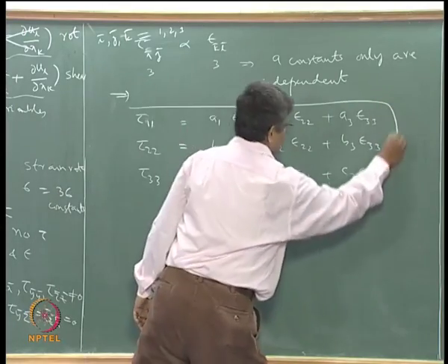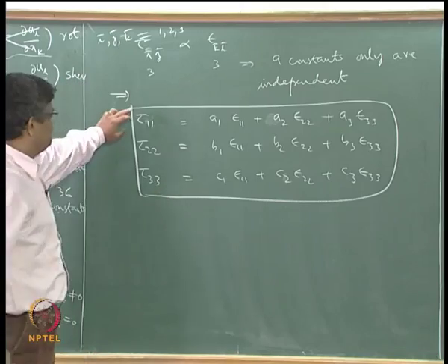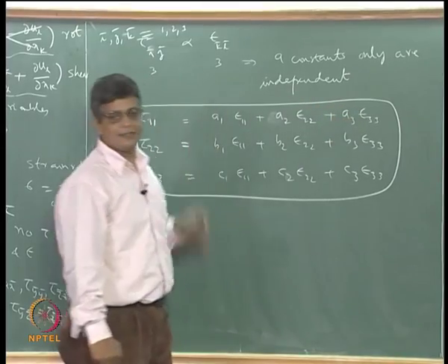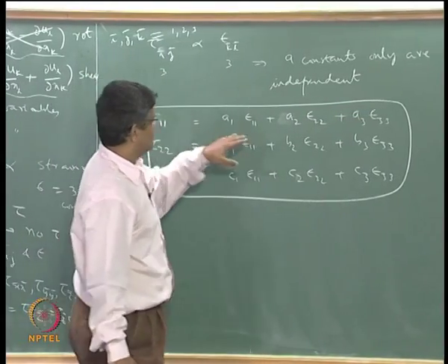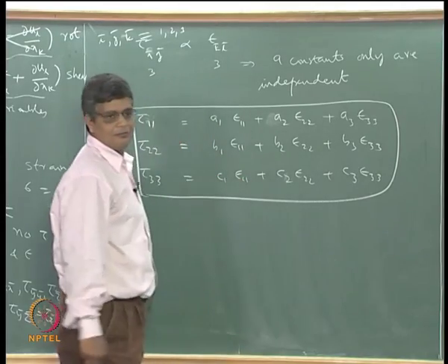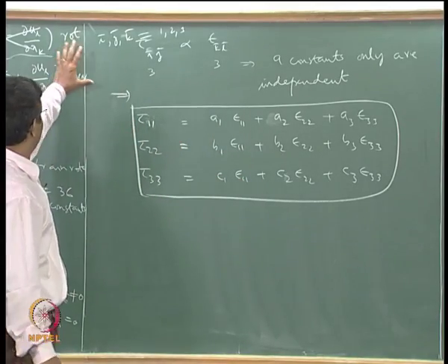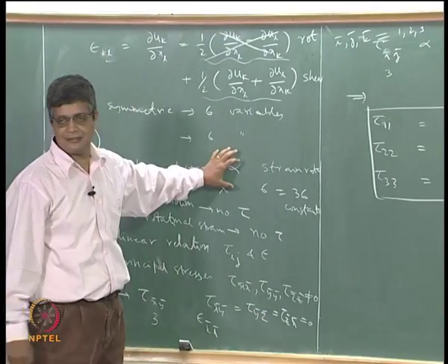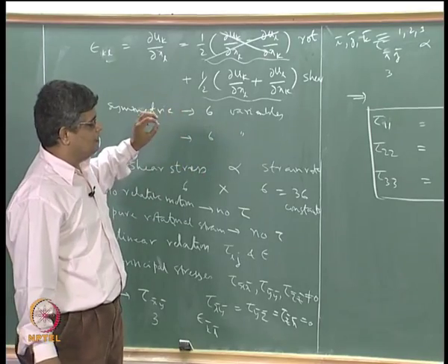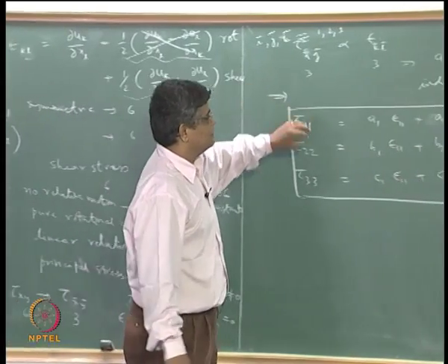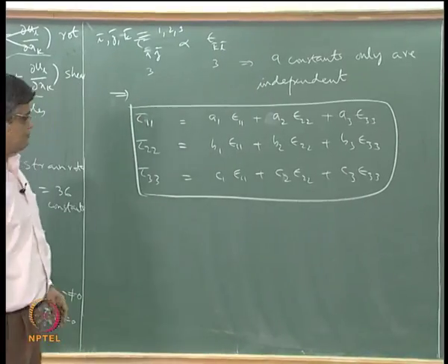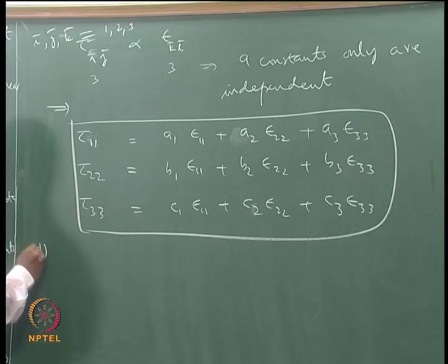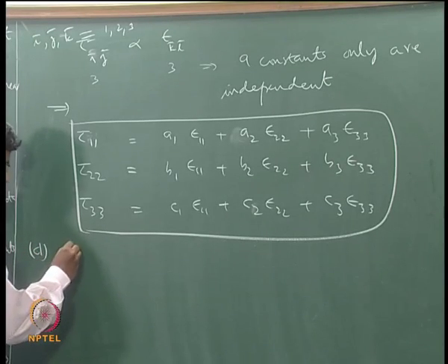Here we have 3 principal stresses being proportional to the 3 principal strain rates involving 9 constants, 3 for A, 3 for B, 3 for C. So, this is what we mean by a coordinate transformation involving 2 symmetric tensors being mathematically invariant, in which there are only 9 independent constants that are permissible. Now at this point we introduce the fourth condition, that the fluid is isotropic.